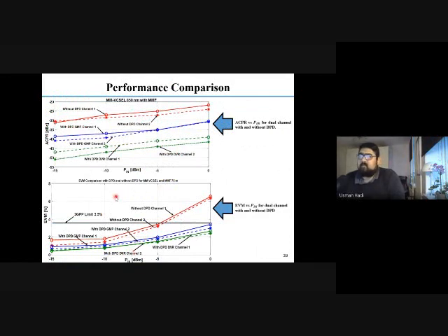When we compare the results with respect to ACPR and EVM, you see here that the blue one, red and green, these two channels have different behavior because they are two different frequencies. They are operating at different frequencies, but the same length. So for example, this is at -20, -25 dBc, which is a very high value at 0 dBm of RF input power.